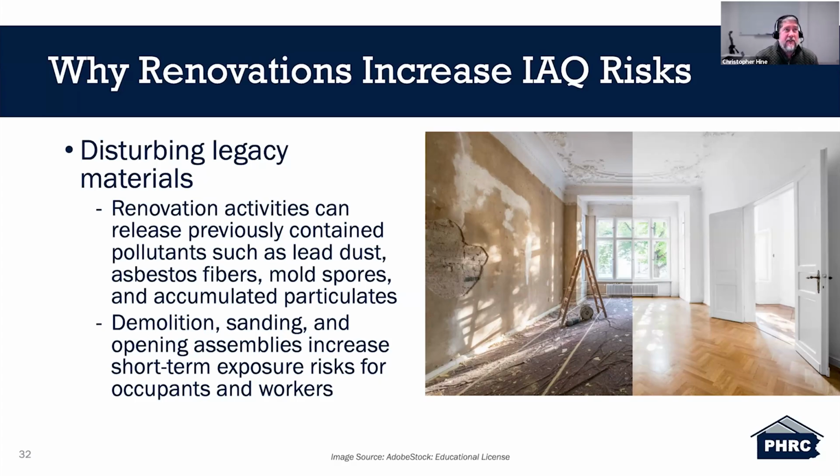So if it's a whole house renovation, there probably is not going to be anybody living there during the renovation. However, if it's an addition or a small renovation to a kitchen or whatever the case may be, there may still be occupants living in that structure. So it's always important that if there's people living there to reduce the risk of exposure, isolate your area off the best way that you can. Start with poly, sheet goods, hang that up, and then try to seal that to the wall or whatever opening you have the best you can to keep those pollutants in the demolition zone and not into the remainder of the house. That kind of goes without saying, but it's one of those points that I just wanted to be sure I covered.